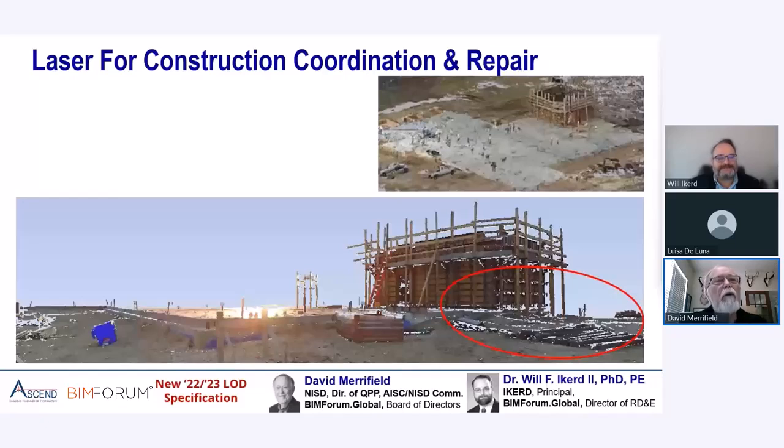So what happened on this job is that after about 5 weeks of the steel sitting on site, we decided that the right thing to do was to have all the anchor bolts on this project scanned, and then take that back into the model and determine what needed to happen at each location to get the project back in so that it could be erected.